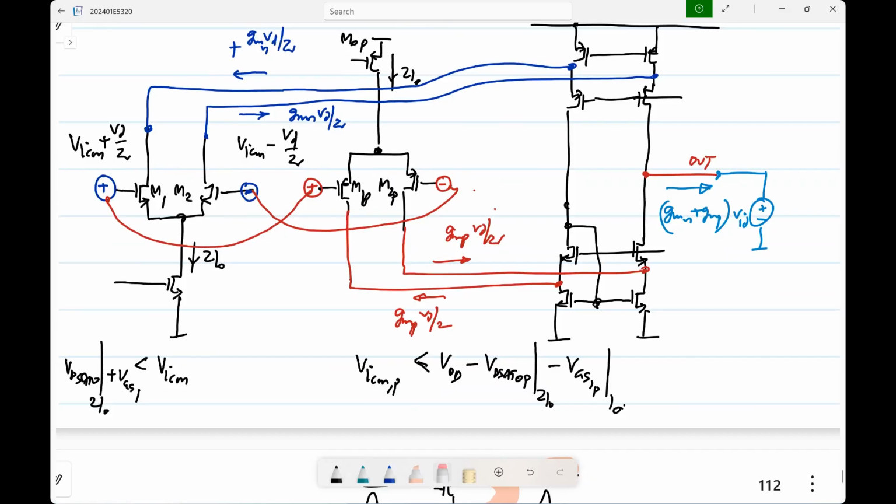So now we understand single stage op amps pretty well. I mean, if you make a differential pair with a current mirror load, you have a single stage op amp. The disadvantage is relatively low output resistance and consequently low gain, right? So we can improve the gain by using cascode, either telescopic or folding. You choose which you want based on the swing and noise and so on.